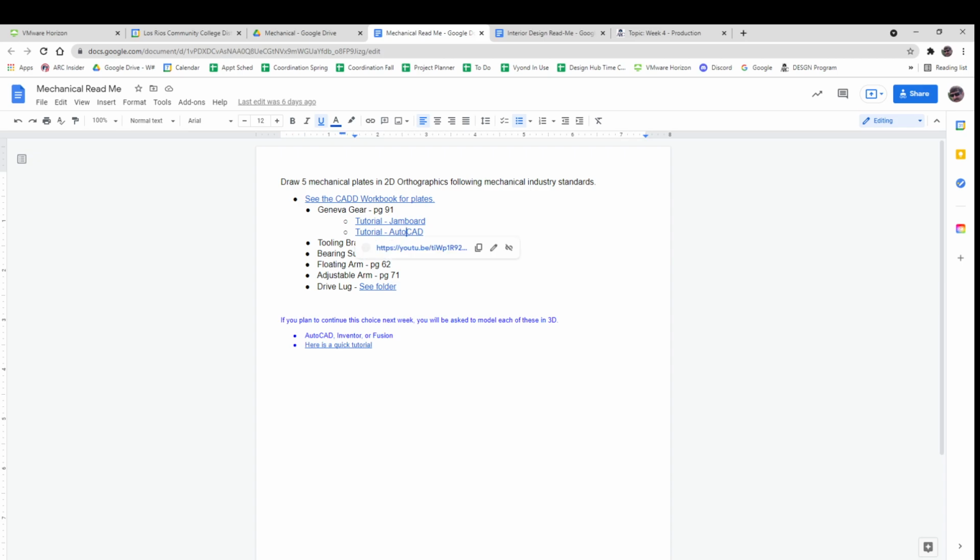If you look, I actually did it on the tutorial. It shows how to do it, but they are not tangents. You actually draw the outside circle, which is like 6 inches or something like that. And then you go out to the center point at 22.5 degrees, draw a circle and trim away what you don't want.